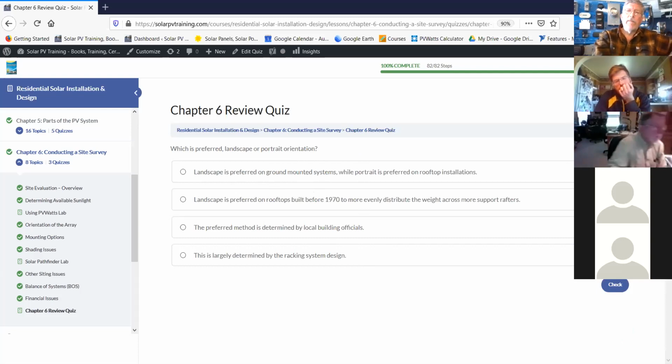One of the nice things about the panel manufacturers in today's environment is if you're going to be installing a system like on a roof or even a ground mounted system, they're going to ask you for your zip code as part of that design. They usually have online design tools. And in fact, I think in one of the upcoming chapters, you'll walk through this. When you put in the zip code, it will automatically put in your wind load factor, your seismic factor, your snow loading factor, all of these other issues that you would have to calculate. They'll build that into your design. So if you're in a high snow environment or a high wind environment, based on your zip code, it will design your system to withstand those. So it might narrow some of the supports, might require more supports, that kind of stuff.